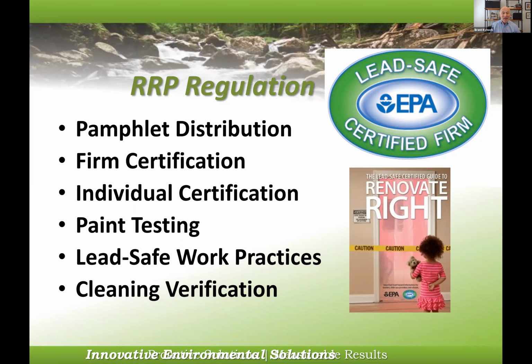Back to the scenario I described earlier, if you're bringing someone into your home to do some work, they should be giving you the pamphlet that you see down there below that says Renovate Right. They should be using lead-safe work practices. Before they actually start the work, they're required to test the paint to determine if it is lead containing, which would then kick in those work practices.